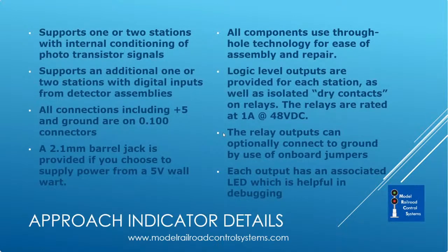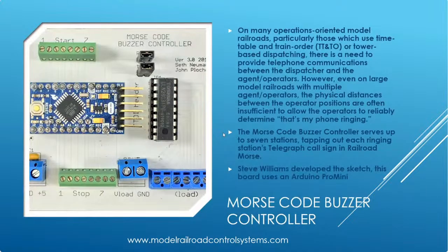And let's see. Okay, this is all pretty much what we've talked through. Here's another one, a little bit older, using the Pro Mini type board. You can see it has a slightly different connector. I'm wiggling the cursor, but if you can't see that, there are 6 little gold pins coming out. This is called an FTDI interface. It's just a different way of programming it. The FTDI cable is easy to use. It's USB at one end, and you just plug it in on that end. And otherwise it's fairly similar to the Nano.